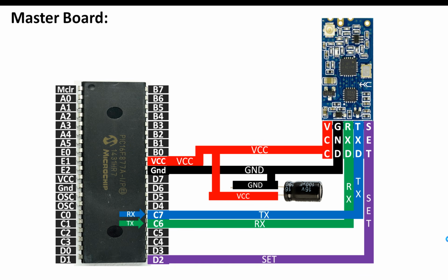Now guys, as shown in the previous slide, we will have a toggle button as well here. I'm going to use this toggle button. It has 3 pins. And to connect any button with a PIC microcontroller, you need a 10 kilo ohm resistor, either to connect it in a pull up or pull down formation. So this is our 10 kilo ohm resistor. In the button, we have one center pin, which we will need. And on the right and on the left of the center pin, we have two other pins. You can use either of the two. We will only use 2 pins, like this. You can leave one pin empty, either the extreme right or the extreme left, but you cannot leave the center pin empty.